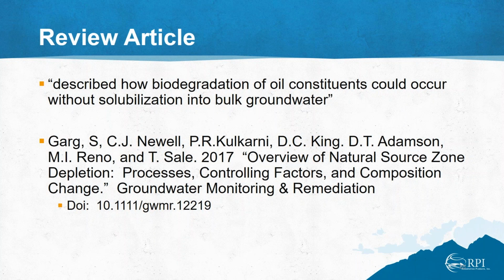I was going to try to share some data, but it's hard to look at chromatograms in a presentation like this, and there are some changes in that. If the person that asked this question could email me, I could actually share some data with you. But we have seen that you don't just get degradation in the lighter fractions. We get degradation across the zone. And you are correct, the longer chain hydrocarbons do tend to take a longer period of time. We've seen this same sort of effect for a long time in the industry.